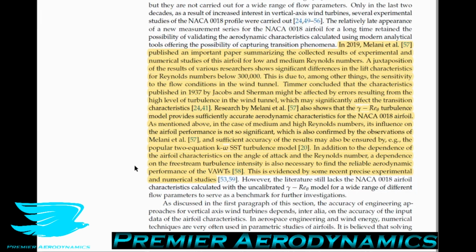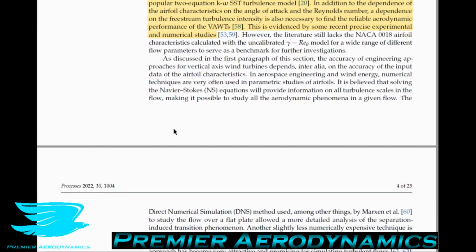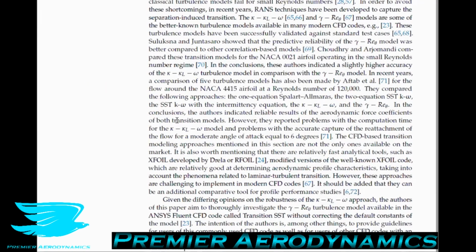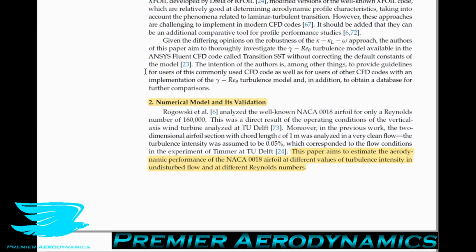The reason why is because this Reynolds number range is very susceptible to laminar separation bubbles, and they are very finicky. Changing just small parameters will change how the flow separates over an airfoil and how it transitions. In the previous podcast, I went through different transition mechanisms. There were 4 main ones that we went through, and if you want to check out that podcast, you will learn a lot about how boundary layers can transition, the different paths they can take, with the laminar separation bubble being just one of them. There are other ones as well. So I highly recommend that podcast here.